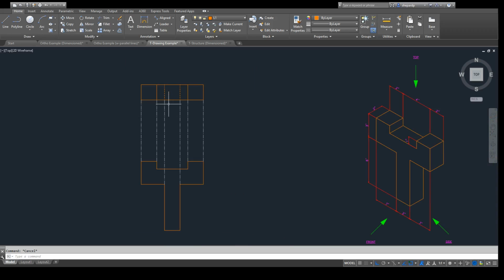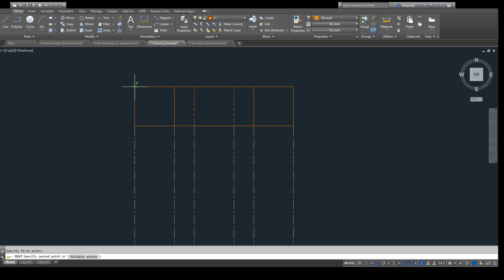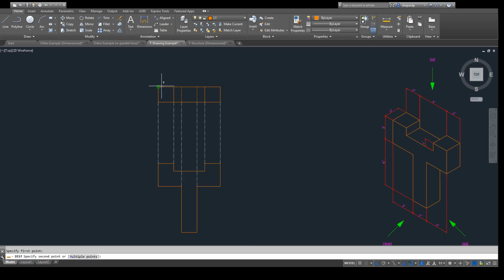Now I'm going to go ahead and double check the line lengths. So I'm going to check my distances using my distance command. This representing the top extrusion is 2 inches. The outside edge to the inside, which is this distance right here, that outside to this inside of the bottom is 3 inches.